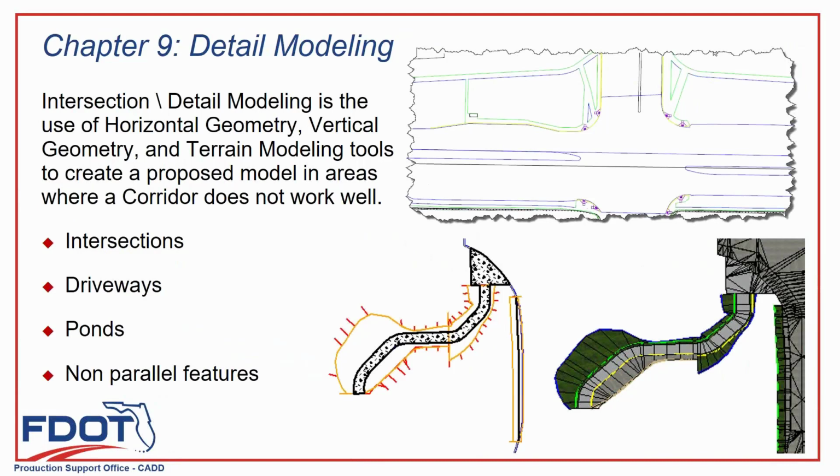Roundabouts, of course. How do you model roundabouts? It's pretty much a series of linear templates. Once you have your controlling lines through the roundabout, it's not just the center lines of the four legs. You've got to have a profile on the radius. You've got to have profiles on each of the returns that go from one point to another. You know how to do transitions. It's now not just two things.